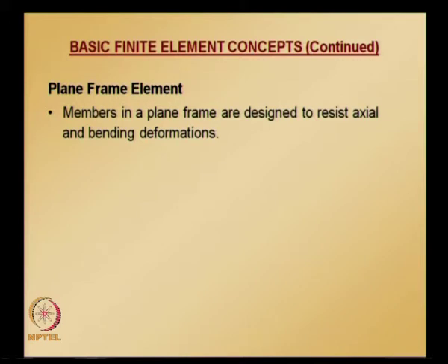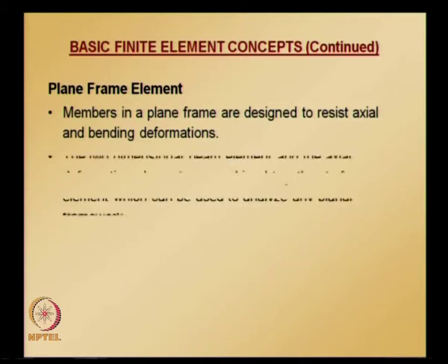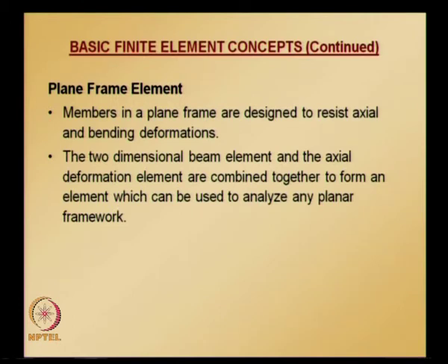Members in a plane frame are designed to resist axial and bending deformations. So it is a combination of a beam element and an axial deformation element. The 2 dimensional beam element and axial deformation element are combined together to form an element which can be used to analyze any planar framework.